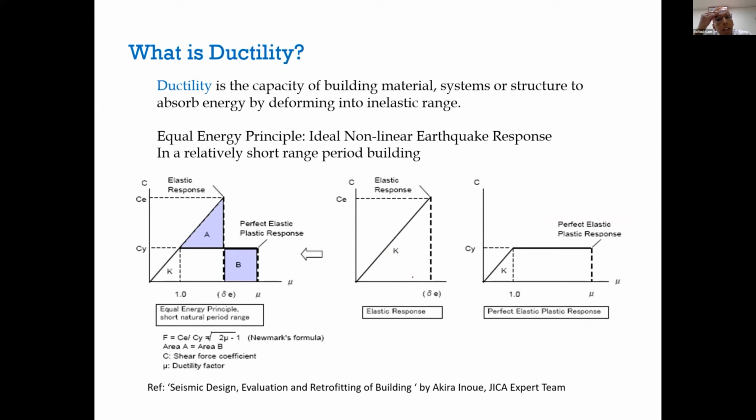Another important term I mentioned is ductility. Ductility is the capacity of the building material, system or structure to absorb energy by deformation into the inelastic range. I think there is almost nothing to say about this. Initially, this is the elastic response of a structural member. This is the force, and this is the deflection.